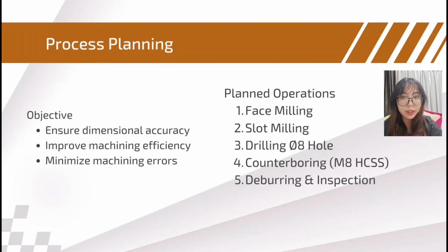Before machining begins, a process plan must be prepared. The purpose is to determine the correct sequence of operations to ensure accuracy and efficiency. For this workpiece, the process starts with face milling, followed by slot milling, drilling, counterboring, and finally deburring and inspection.